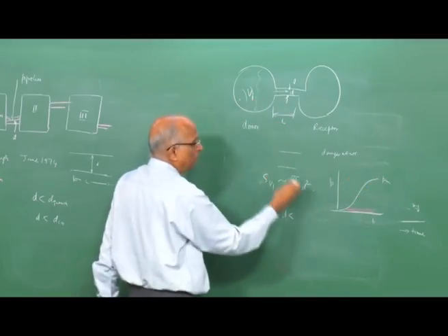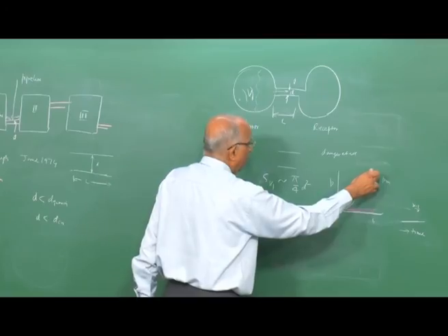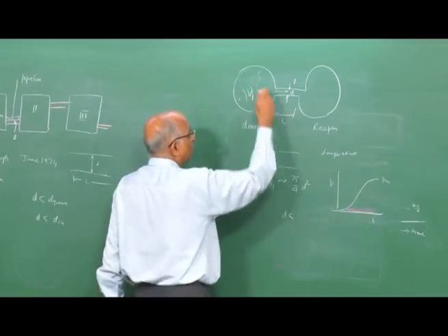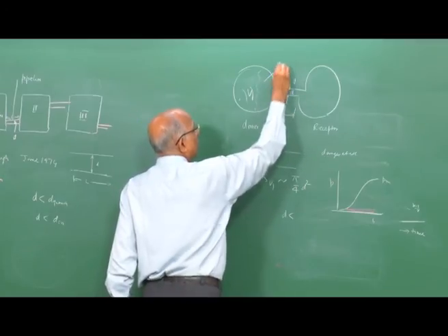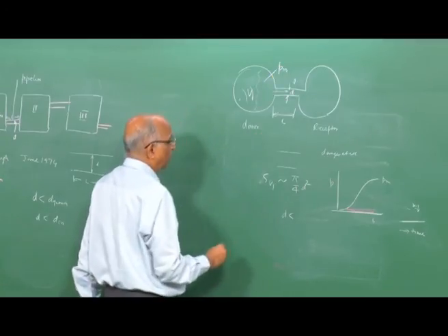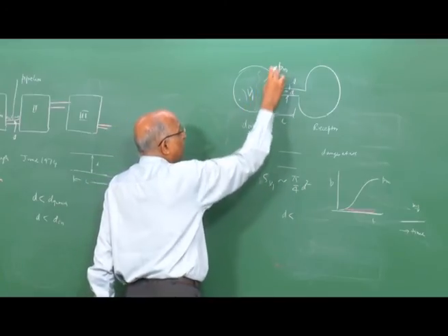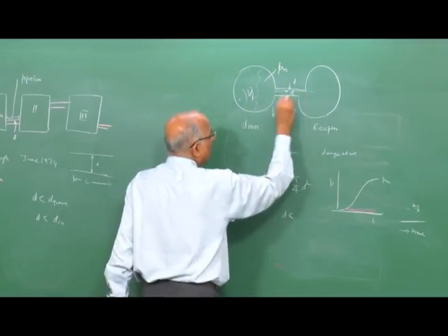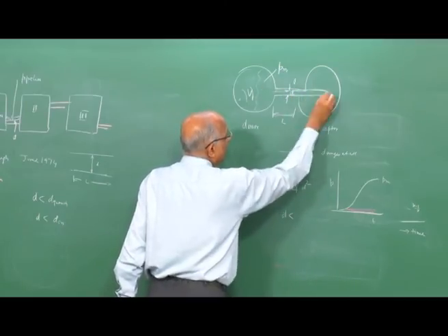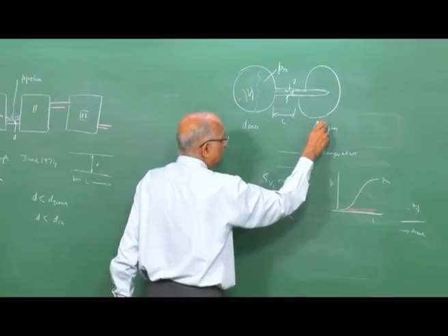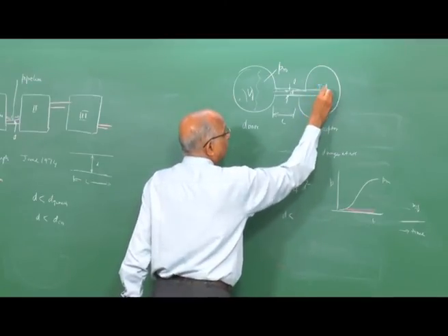which for hydrocarbons we said is between 5.7 to something like 7 atmospheres. If it is hydrogen, it is of the order of 11 atmospheres, and therefore I have a constant volume explosion which gives me a high value of Pm. And therefore what is going to happen? You have a high value of Pm, and therefore the gas comes in here at high pressure, and it expands into this receptor vessel, let's say V2, as a hot jet.